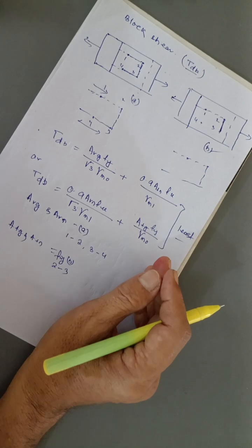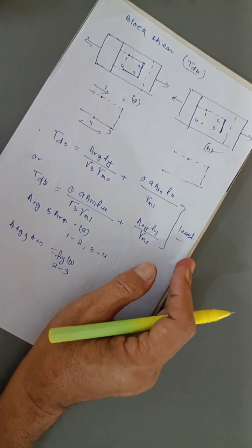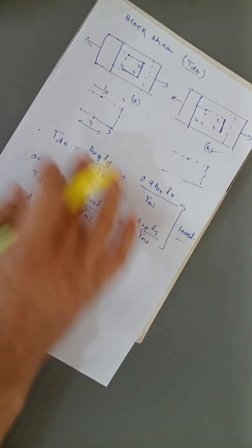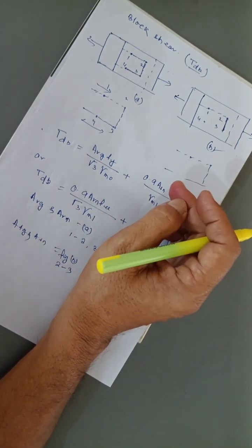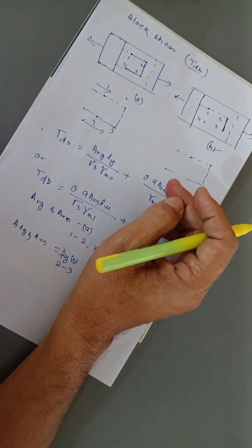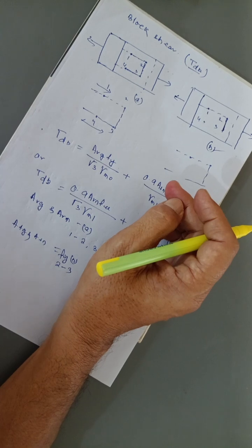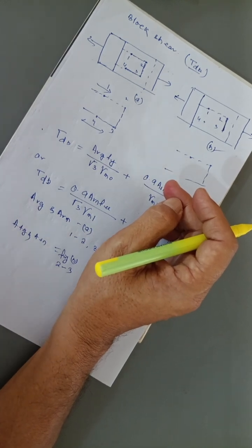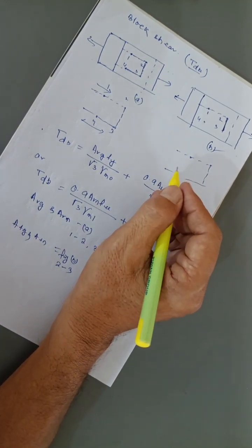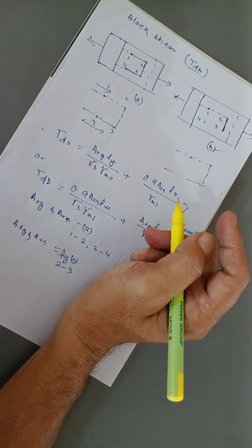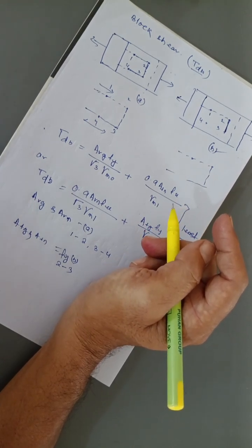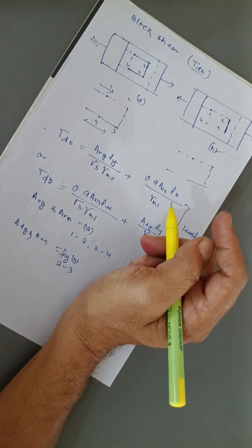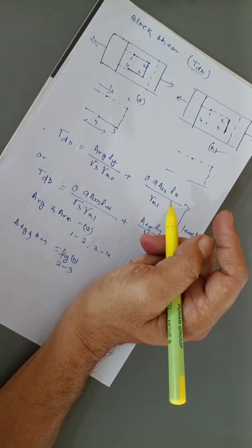These are all in bolted connection. In case of welded connection, the block shear strength TDB for welded end connection shall be calculated by taking the appropriate section in the member around the end weld. We are considering this.